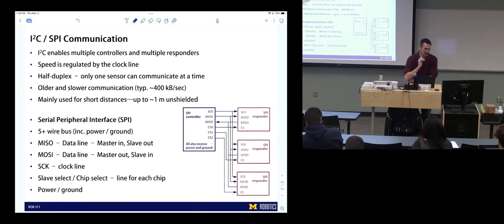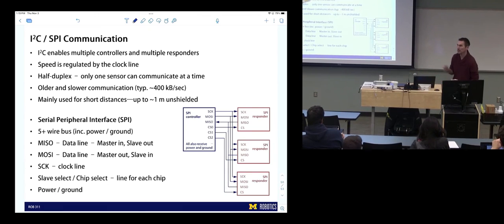Is it true that the time on the communication bus, the time it is required to send messages to your various peripherals, is that an important amount of time or not important? Is that significant or insignificant? It's actually significant. I've mentioned this off the cuff one time, it's not in the slides, but the time it takes to send messages on the bus can be a huge driver of your system's loop timing.